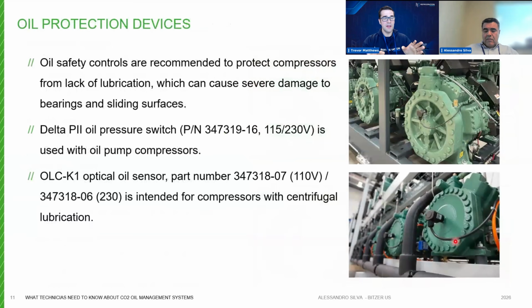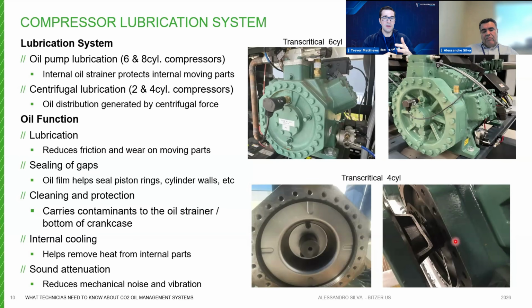Wow. Yeah, that's super important, because you've seen it even with HFC compressors: if you're low on oil, there could be more vibration in any compressor. It doesn't matter the compressor. If you've got low oil, there's more vibration and more noise. So that makes so much sense. Exactly. Yeah.